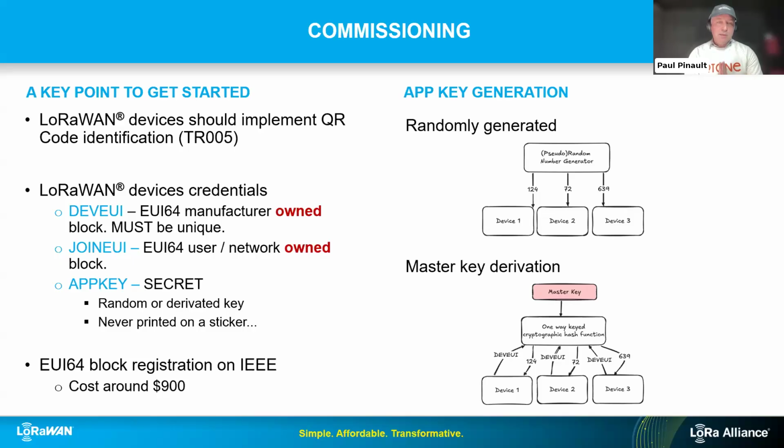The last point about security, which is really, really, really important, is the AppKey. The AppKey is a secret. It's like the PIN code for your credit card. So do not put it on a sticker on the device, and don't reuse the same secret for every device.